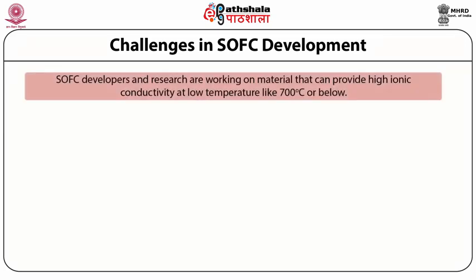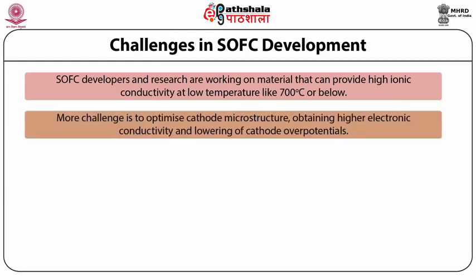SOFC developers and researchers are working on materials that can provide high ionic conductivity at low temperatures like 700 degrees Celsius or below. This will significantly reduce the cost and simplify operation compared to high temperatures. More challenging is to optimize cathode microstructures, obtaining higher electronic conductivity and lowering of cathode overpotentials.